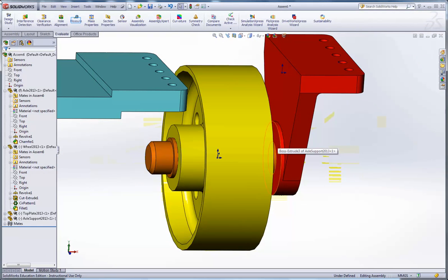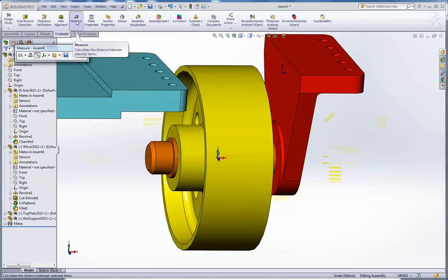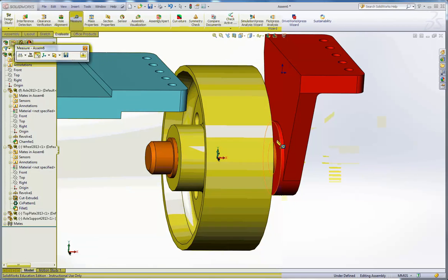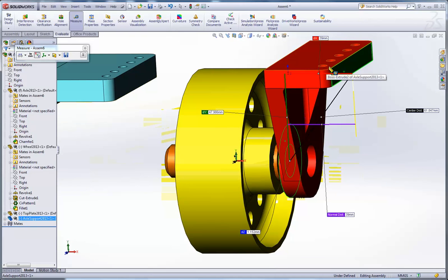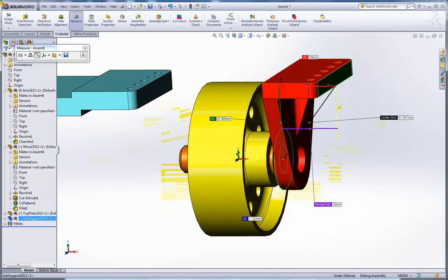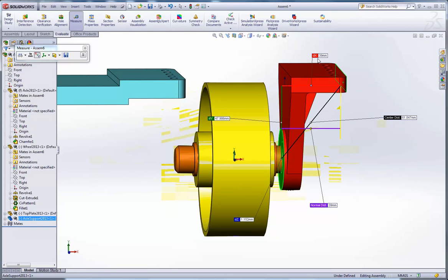So measure, let's do that again. Pick the face, and I'm looking for this X distance. You can see the red line going across is 39, so we had chosen 37. The extra 2 millimeters has come from that boss. So let's recalculate that. If I subtract from the base of the top plate, which is 136 millimeters, minus the 39, minus 39, that would give me 58 over 2. And 58 over 2 is actually 29.